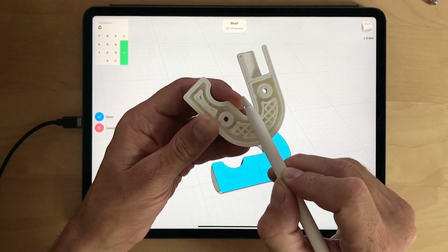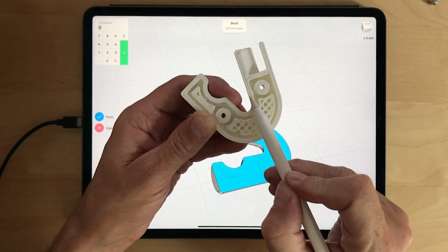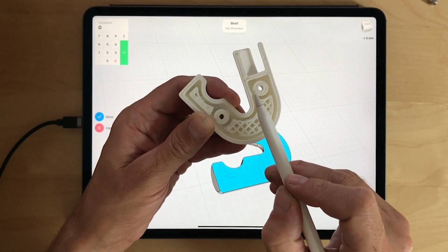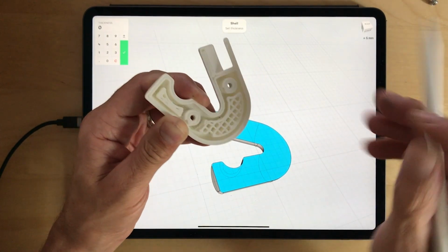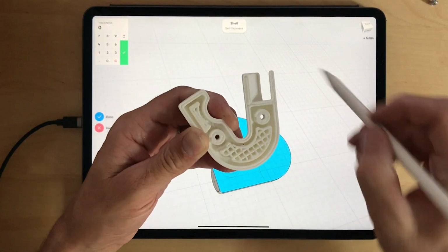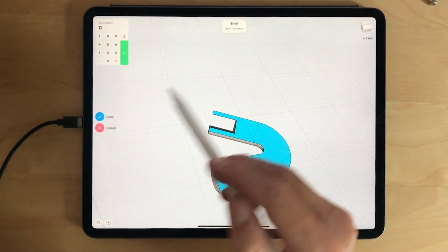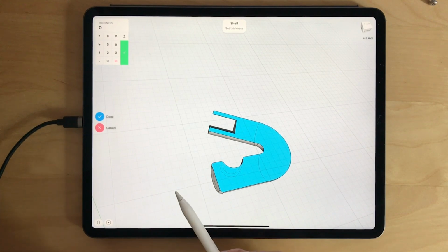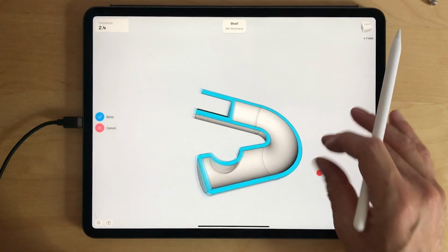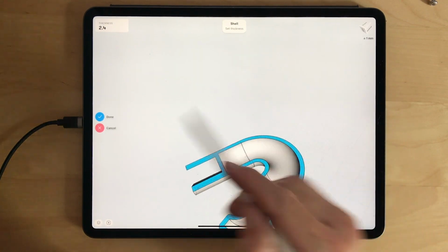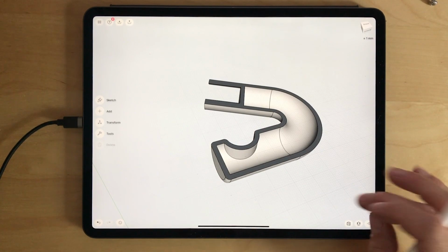When this is a 1.2 millimeter print width, then the layer thickness should be equal, double, triple, or 4 times, but not like 2.5, because the printer has to just go along the lines. So 1.2 multiplied by 2 is 2.4 millimeters. Okay, so that looks pretty good. So that's now the material thickness for the shell.